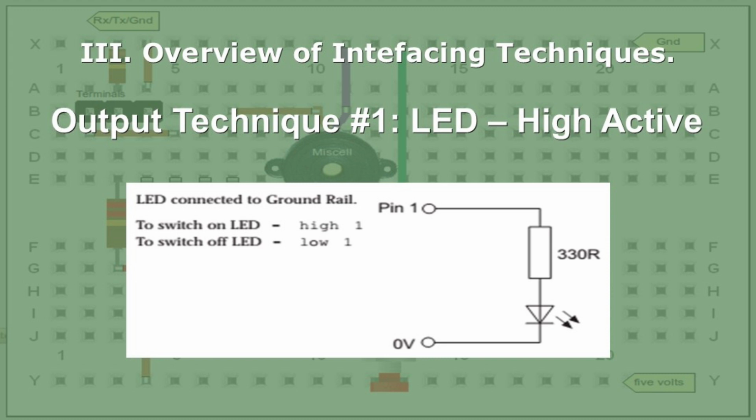Now a lot of modern microcontrollers today are 3.3 volt outputs. And now I'm going to ask Gordon a question on that. Do they still use a current limiting resistor even with a 3 volt output if they want to run an LED? Yeah, you better. That's what I was thinking. Otherwise, your LED will not like it because it typically doesn't like more than 2. It'll tolerate 3 volts, but it will be very bright and may not last too long. And on 5 volts, it will glow even brighter and not last long at all. And if you put 12 volts to it, it'll go like a firecracker.